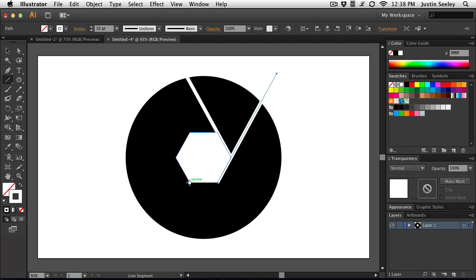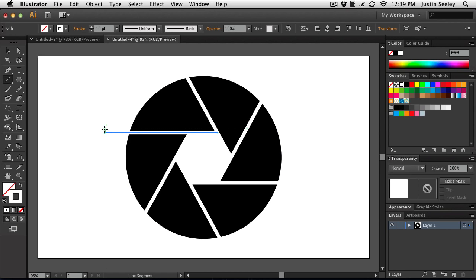Now we'll draw this one straight across. So just come here, hold down the Shift key, and click and drag across like so. The next one's going to come right here. Drag this down. It's going to be at 300 degrees. And there we go. Now we'll come to this one. This one's going to be at about 240 degrees. Straight down, just like that. And then finally come to this corner and draw another straight line just off of it, like so. There we go. So there's all of our little lines.